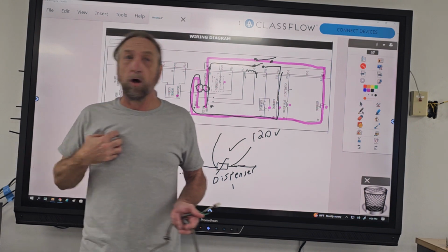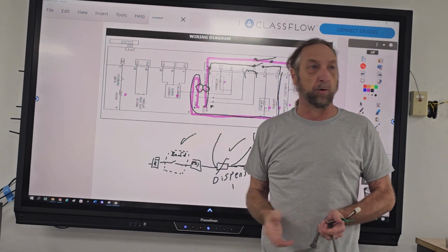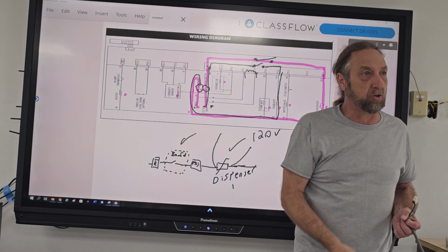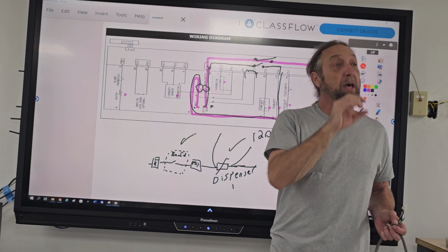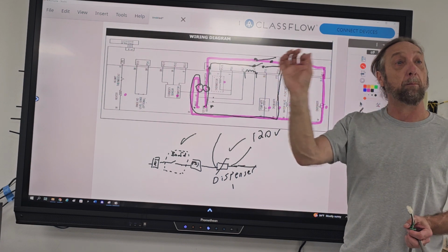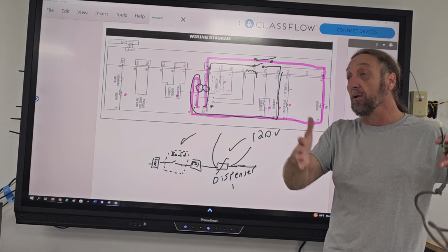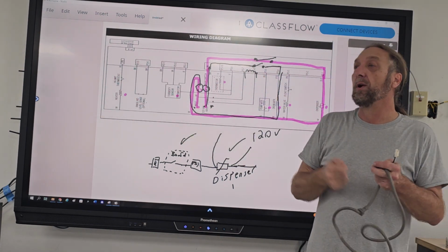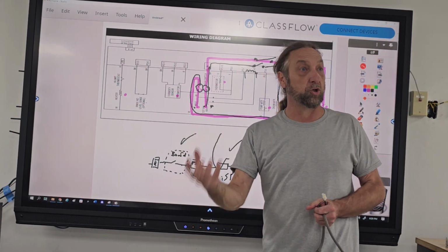And if you don't know the circuit, call me and say, hey, I'm trying to figure out how this thing is getting power, how it's working. I can't follow through this diagram. Call me. Because I want you to see those circuits. It's the same thing with the light board. You're just practicing tracing circuits. If you can trace the circuit of a part, by finding that circuit, you know what parts you need to test to troubleshoot. And we can make it smaller and smaller. If we could say what parts are working, what parts are not, we might be able to eliminate them so we're not having to test 10 or 20 parts. But that is the troubleshooting of it.